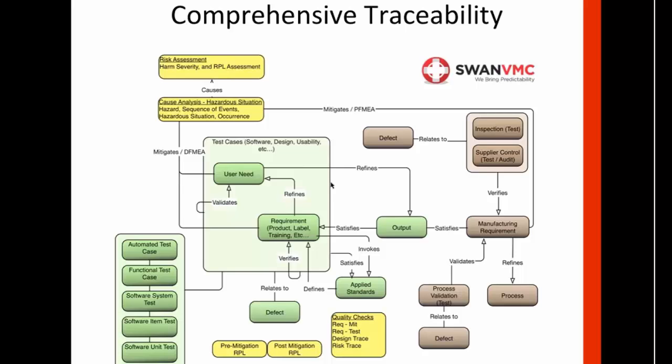So what we have with the specifications is a list of both the product prints and parts that are used to build the product, but also code, work instructions for fabrication of the product, inspection steps, all that. So really what this output list ends up being is your DMR. So we want our device master record, or the recipe for the product, to be tied into our requirements, so that if we have a problem with those, we have immediate tie out into the requirements and user needs that are being satisfied by that part.